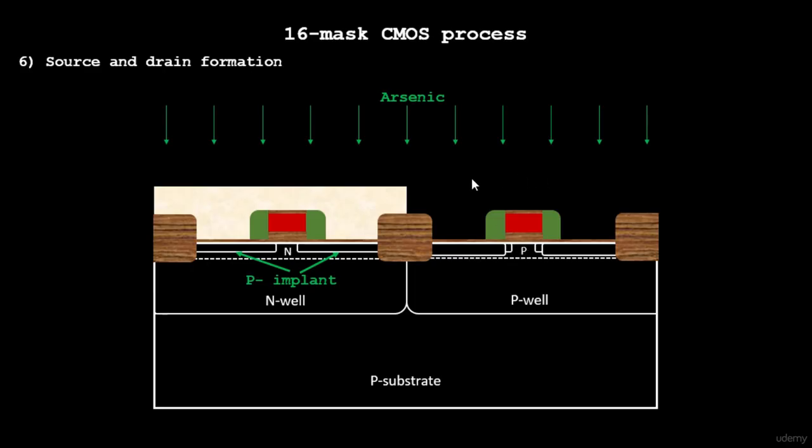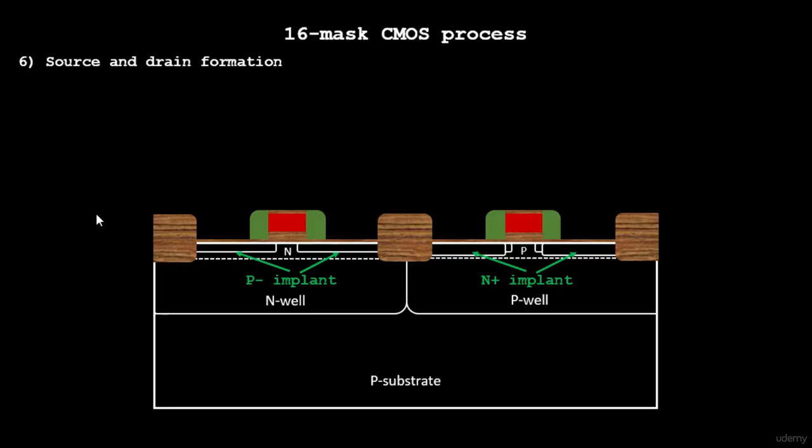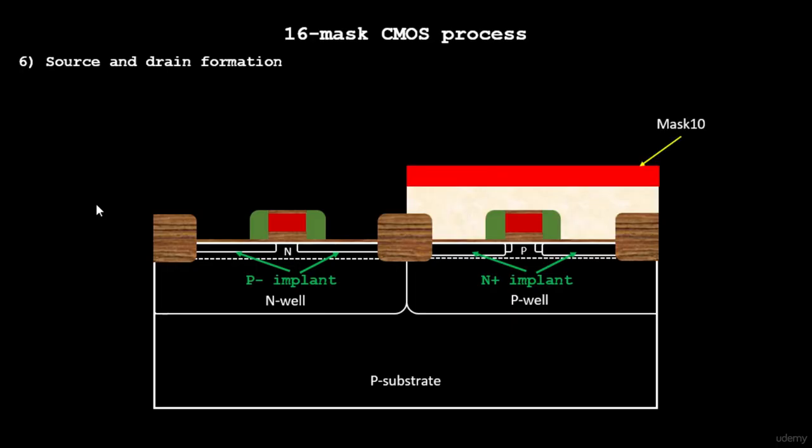This is the general energy barrier maintained between the conduction bands, and if a carrier crosses it, it might enter the oxide layer which is present just above your substrate, and it might create reliability issues. So this is the hot electron effect.